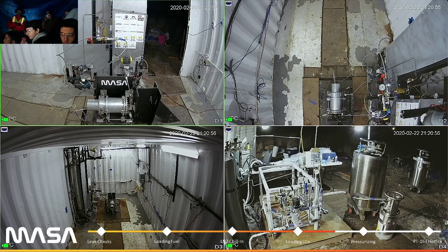Okay, Jeff? Alright, let's do it. We're beginning LOX-Ethanol. Let's open up the vents. Yes, OXS and GO2. Do you need any pneumatic pressure first? We're not moving, because then people will yell at me if I try to talk. HES and J1 for 4 seconds. The helium tank is at 160. And then pneumatic vent first. No, OXS and GO2. Very shortly after we finish LOX fill, we fire the engine.